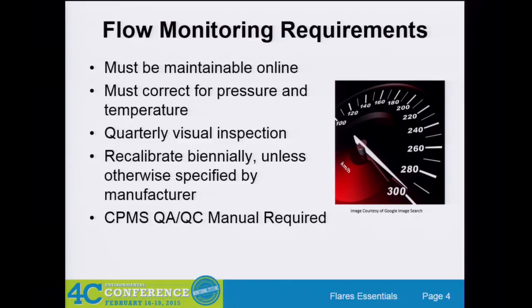It's actually not that difficult to do. Basically, with the GE ultrasonics, you're installing a valve right off the tap, where the flow meter can retract back beyond that valve. You can shut the valve and then get to the flow meter. So it is possible. You must correct too, you need to measure pressure and temperature so you can correct to STP.